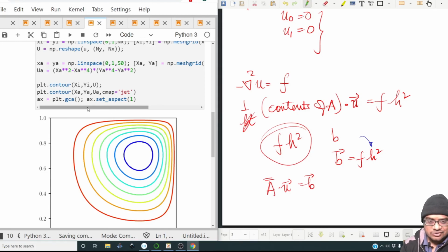So with this strategy, you can pretty much implement any boundary condition you have. You can use the ghost node strategy to implement the Neumann boundary conditions as well. I have not discussed it over here, but it is a straightforward extension of what we had done for the one-dimensional case a few lectures ago. So with this, I am going to end this particular lecture and this week.